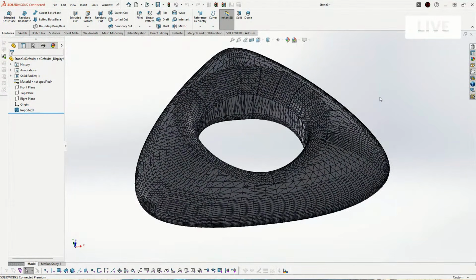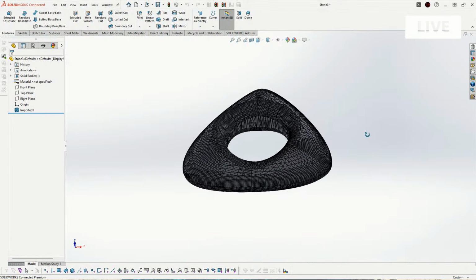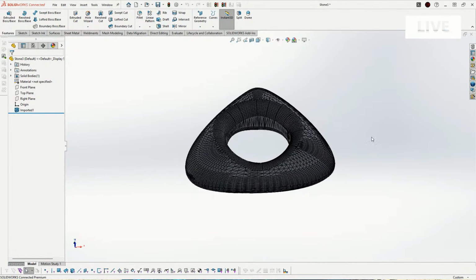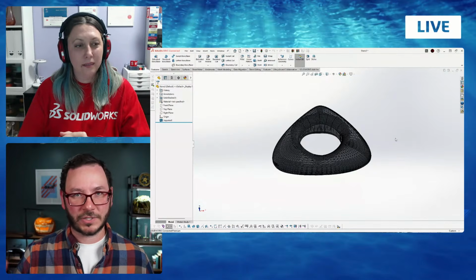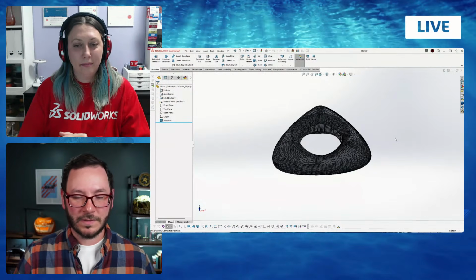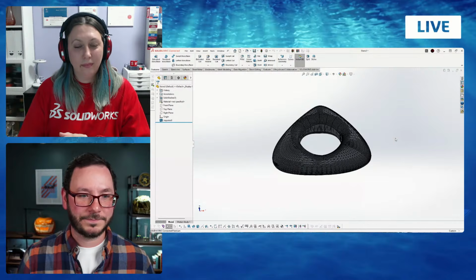And if you have a very complex STL file, it won't work, probably. Yeah, just too much data, right? Yeah. So that option would probably really only work in cases where you have a very simple STL that's probably already pretty geometric already that you wanted to do something with. But otherwise, your recommendation is basically go the opposite direction and then convert it backwards when you need.